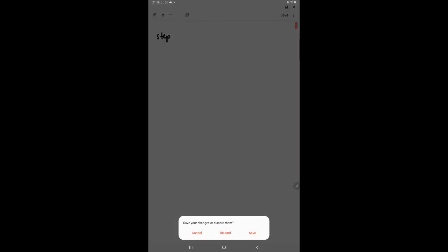If we take a look at the question, the first step is basically the conveyor. So step 1 is conveyor on. This is the starting trigger, and you should also have the ending trigger. The conveyor should be on, and the ending trigger is the stamping sensor detecting the product. Step 2 is that we need to turn on the stamping cylinder, and at this point the conveyor is off.